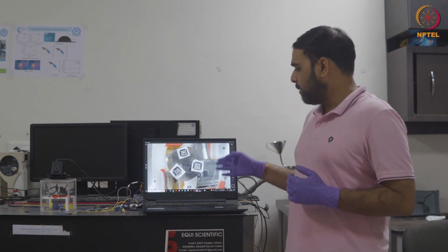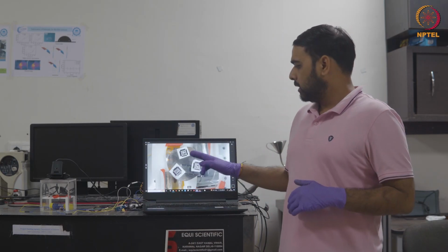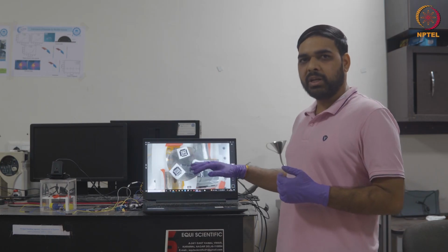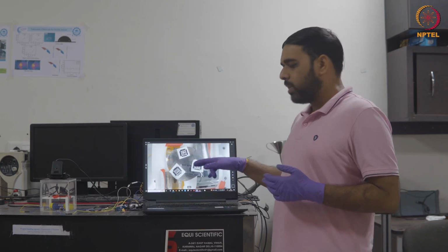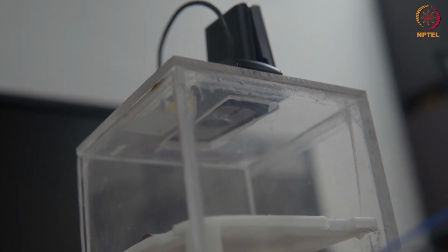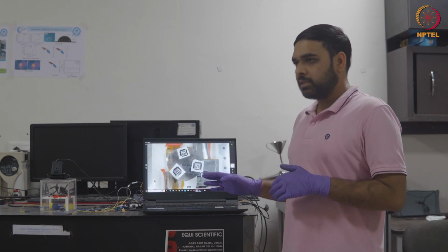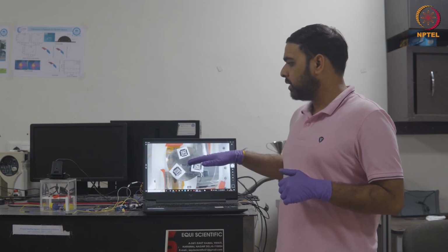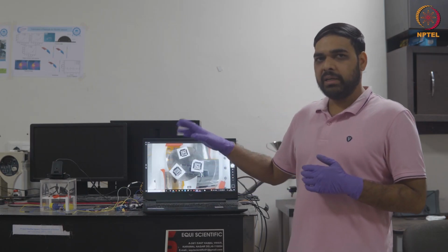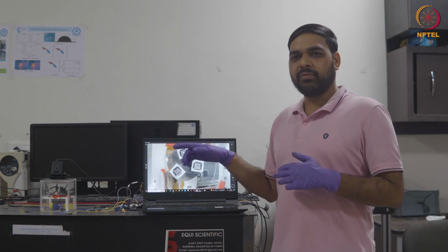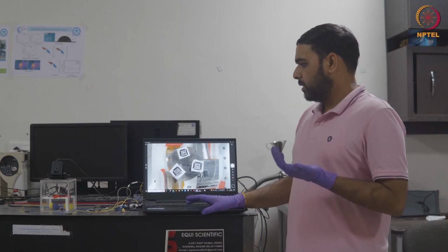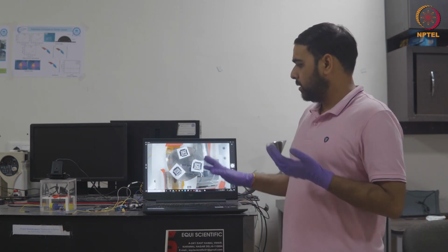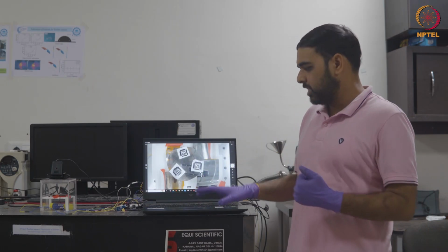And as we supply power to any one of the actuators, this mirror will tilt, and because of that tilting, the position of the ArUco markers with respect to our camera will change. As it changes, the new position will be detected by the camera, and it will again generate the equation of a new plane and give the final angles of the plane, or the mirror, with respect to the initial position.